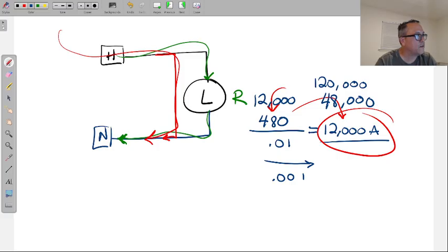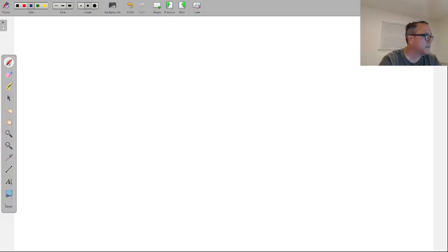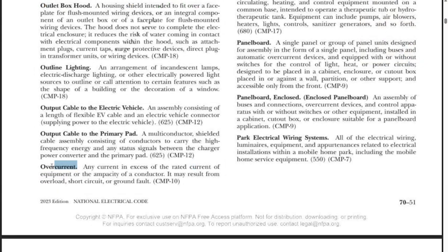This is why if you ever watch those videos on Instagram or social media or wherever where you see a short circuit on a power line and it's just a massive explosion, that's why, this massive amount of amperage just rushed into this circuit. And it can potentially cause fires and everything. If breakers and fuses don't trip, fires happen along the way. So all of this, too much amperage being plugged into the outlet, or a short circuit or a ground fault causing this massive inrush of amperage or inrush of current, now to go back to the definition, falls under the umbrella of overcurrent. So just take note of that.